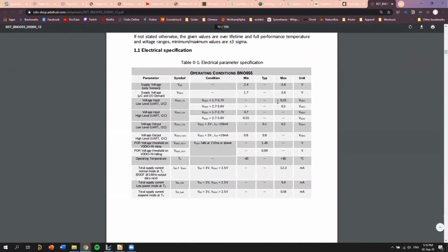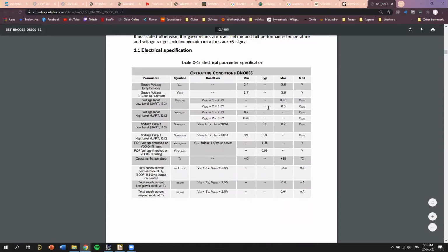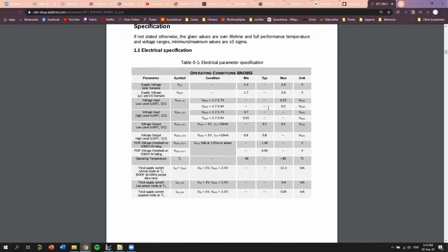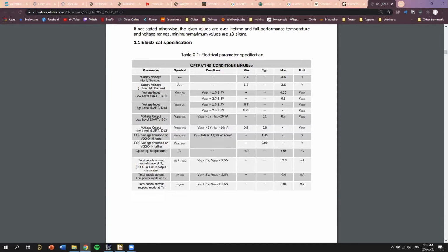So if we're expecting in the future to use a 9-volt battery to power the electronics on a rocket, or a LiPo battery, you're going to want some sort of filtering. The voltage will normally be a bit too high for this sensor. So we want some way to step it down into the range that this is going to run off.